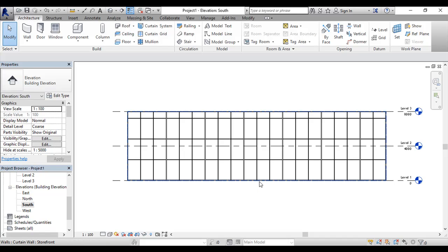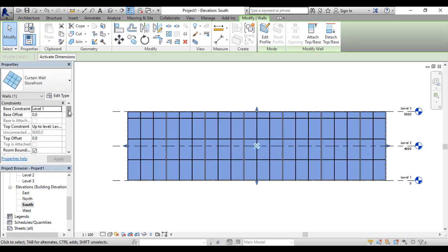If I click on the whole wall, you can see that Revit, as we said in the second video, the justification beginning for the vertical means from the left, and for the horizontal grid, it's from the bottom. That means it starts with a certain height up to where there's no more height, so the leftovers will be at the top.